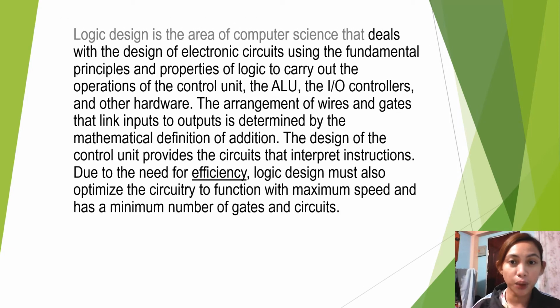Logic design is the area of computer science that deals with the design of electronic circuits using the fundamental principles and properties of logic to carry out the operation of the control unit, the ALU, the input or output controllers, and other hardware. The arrangement of wires and gates that link inputs to outputs is determined by the mathematical definition of addition. The design of the control unit provides the circuits that interpret instructions. Due to the need for efficiency, logic design must also optimize the circuitry to function with maximum speed and have a minimum number of gates and circuits.